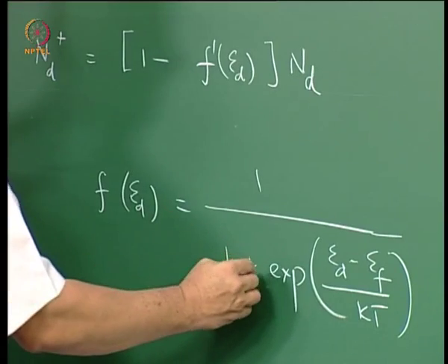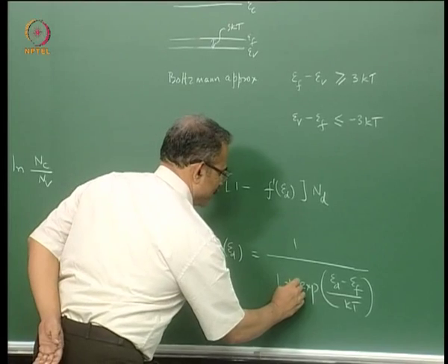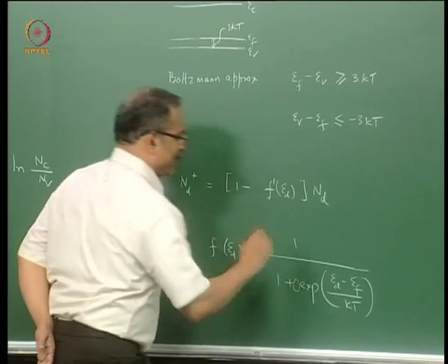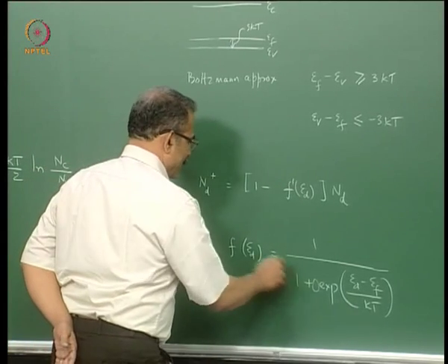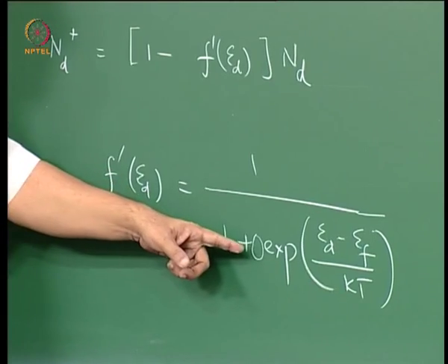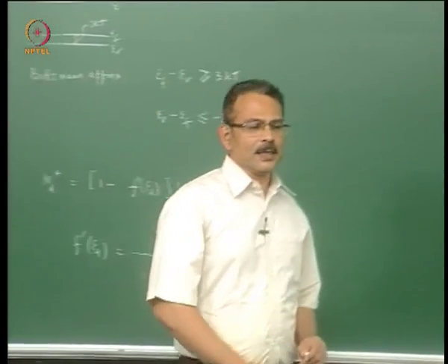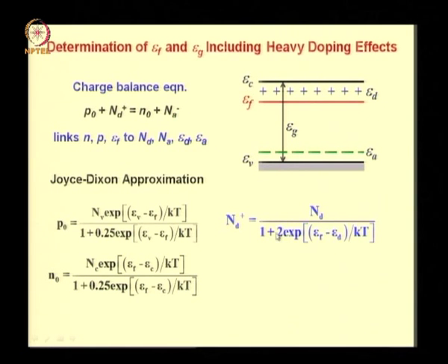But when you are applying the function to impurity level, there is always a constant coming here. It is called a degeneracy factor, and that is why you use a different function than the Fermi-Dirac function. It is because of this factor that you have 2 coming in here.